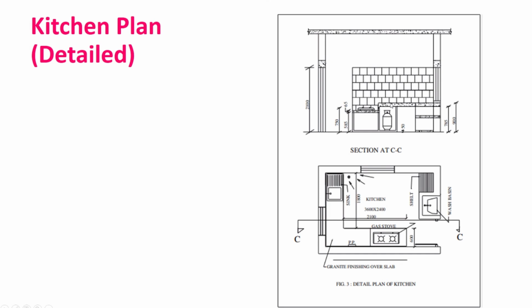Now there may be certain provisions. Many times it says that your building or plinth height is supposed to be around 45 centimeters above the road level, suppose. So what it says is that the street level or the grade is the officially established elevation or the grade of the center line of the street upon which the plot fronts, that means whatever road is in front of that particular plot. If there is no officially established grade, the existing grade of the street at its midpoint is required to be taken as a reference.